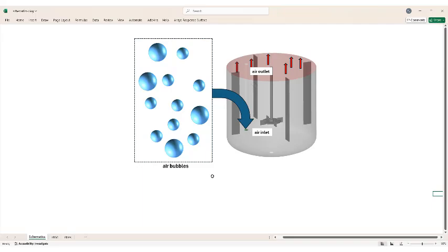But here we're not adding air as a continuous phase in the same way as water. It's added as a population balance phase, which means we are considering air as droplets or bubbles in this case. So the population balance model is a popular option for modeling things like droplet dynamics, as well as particle dynamics, either solid or liquid or gaseous particles. In this case, we're modeling gaseous air bubbles in water.